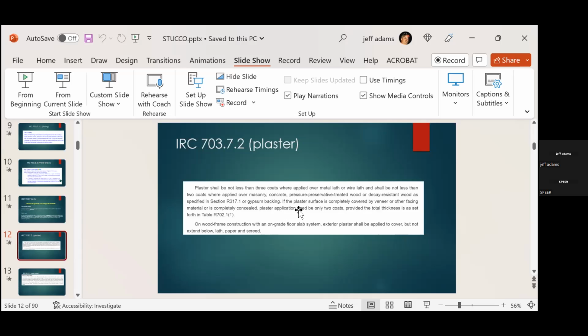There is, like I said, a product out there called Western One Coat, and it's a one coat gypsum. And the problem with those is, again, they don't really completely comply with the ASTM standards. They do have it approved through their ICC evaluation. But you're putting on large amounts of plaster. They tend to crack a little bit more. So I'd rather keep it to the 3 coat when possible, help alleviate some of the cracking.